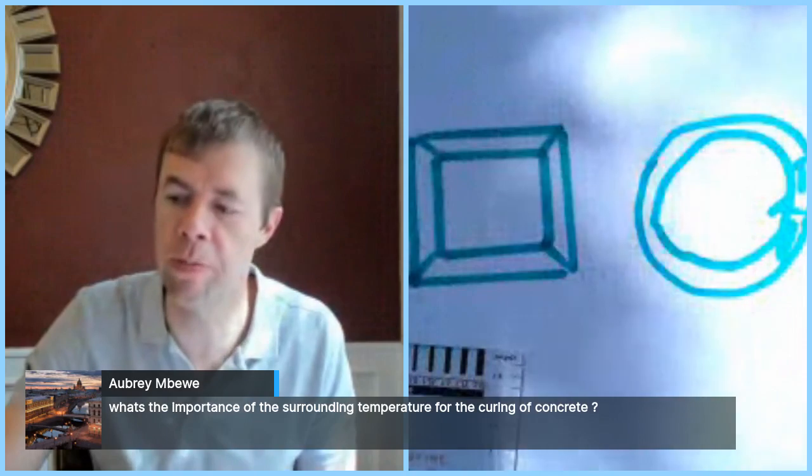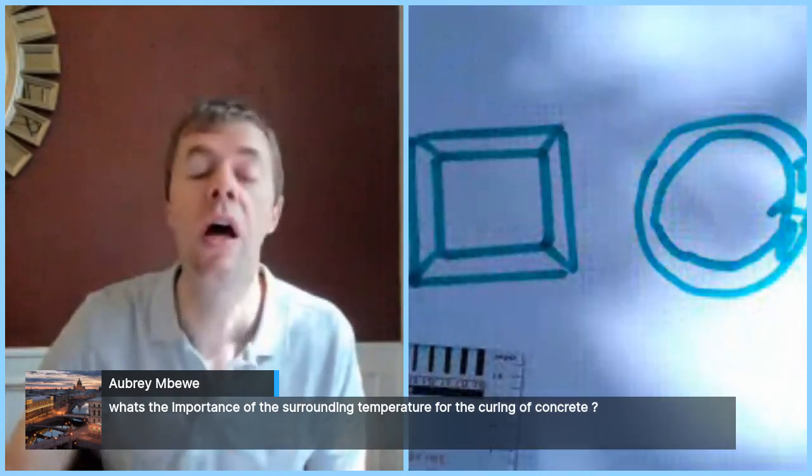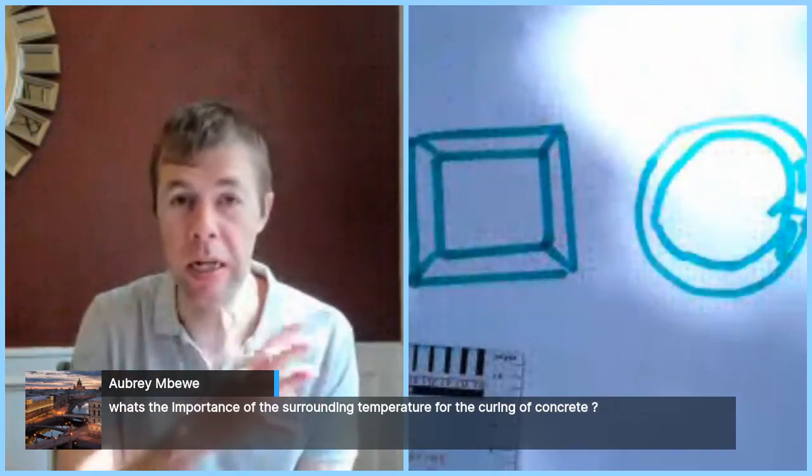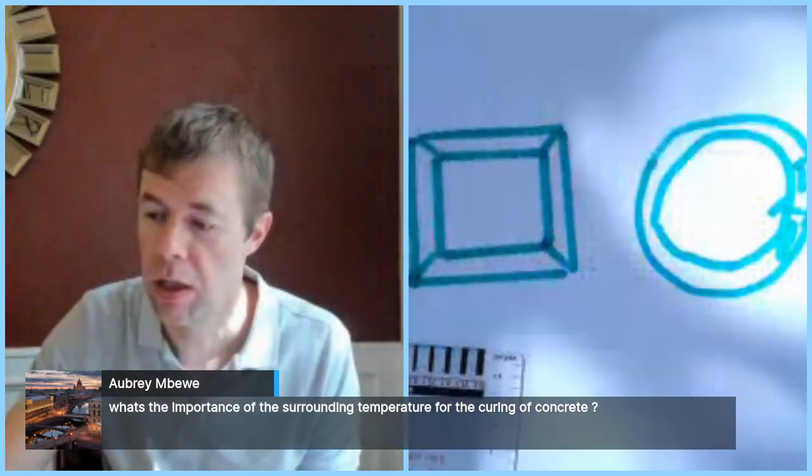Aubrey wants to know what's the importance of surrounding temperature following curing. You want to keep your concrete at a consistent temperature if you can. You don't want temperature differentials.